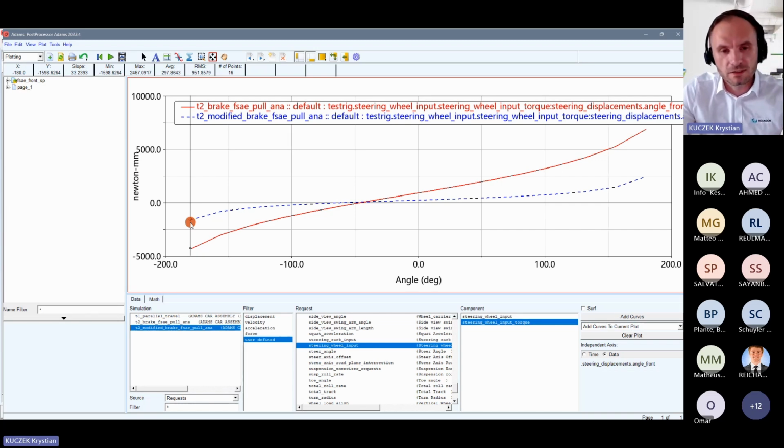And of course, changing the design position of our upper control arm has an influence on our stability. It will also have an influence on our scrub radius again. In this respect, our goal is to have better performance during the braking scenario when the car is, for example, located in a curve, and to have better performance in your simulation results.